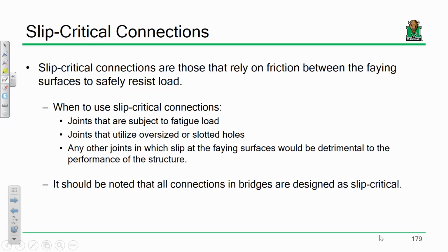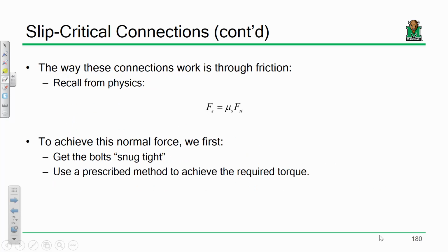Bridges, particularly spliced connections in bridges, are all designed with slip critical bolts. And again, this was the illustration I mentioned last time about the lawnmower. If you have a loose bolt on a lawnmower and you run the lawnmower, it'll vibrate off. Well, that would be low cycle fatigue, not very many cycles and poof, it pops off. We're in a little bit of a different scenario.